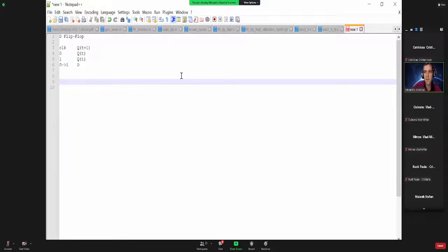And actually the clock signal ensures this kind of synchronization, so that all registers will load their data at the same time. So that's why the clock is called synchronization signal, and that's why you have synchronous logic, because you load into the memory elements, in this case the registers which are composed of D flip-flops, at the same time, okay.